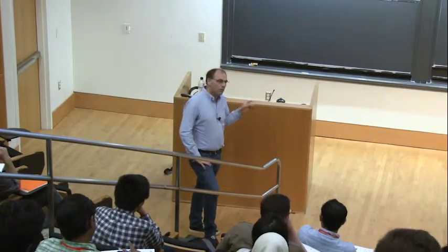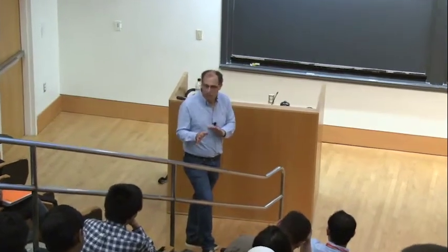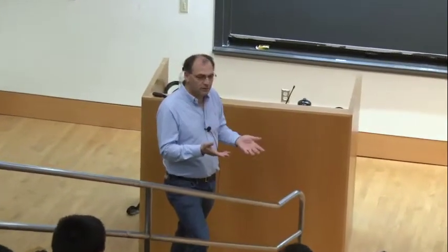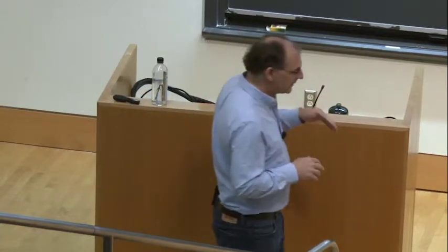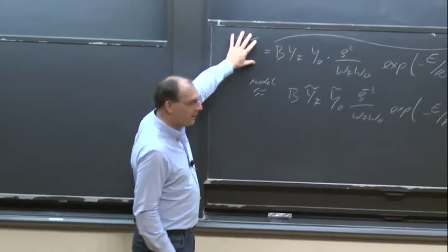And when we talked about laminar flames, we saw that for premix and non-premix flames, this is very, very different. It's entirely different if I talk about a premix or a non-premix flame. And if we now model a chemical source term, that's another thing I said earlier, we cannot just model the chemical source term just by itself.